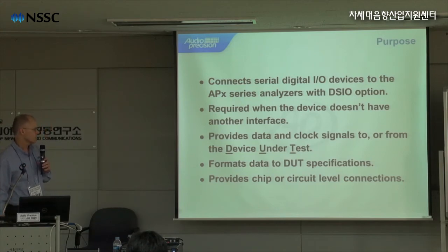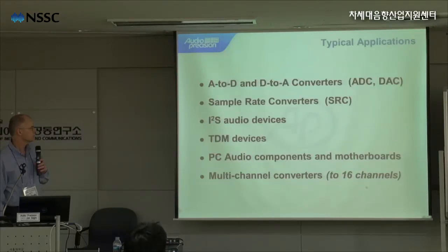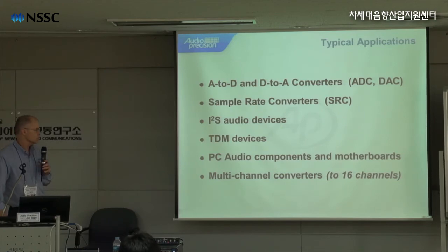It provides data and clock signals to or from the device under test, formats the data into the format required by the manufacturer, and provides chip or circuit level connections. Typical applications are A to D and D to A converters, sample rate converters, I2S audio devices, and TDM devices.